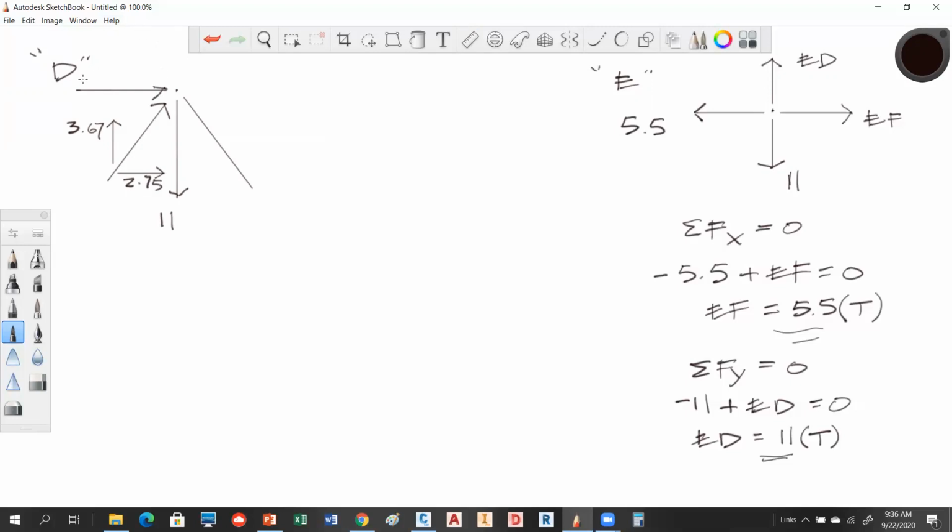And I think, was that 275 as well? Yeah. 275, okay. So now we need to determine which way this is going. And this is pretty easy if you look at it. If this guy and that guy add together, this guy has to counteract it by going that way, right? So doesn't that tell me this guy has to be compression?